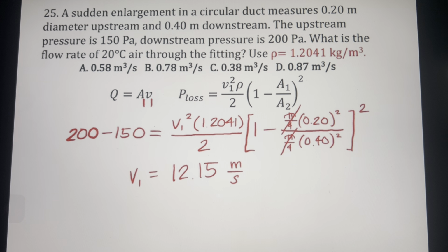27. Determine the heat extracted from 2,000 kilograms of water from 25 degrees Celsius to ice at negative 10 degrees Celsius. So we have here heat extraction from water to transform this into ice. So first, we must bring the water to its freezing point, and then we can now change the phase from water to ice, and then we can further lower the temperature of ice to the desired temperature. So this is actually a combination of sensible and latent heat.